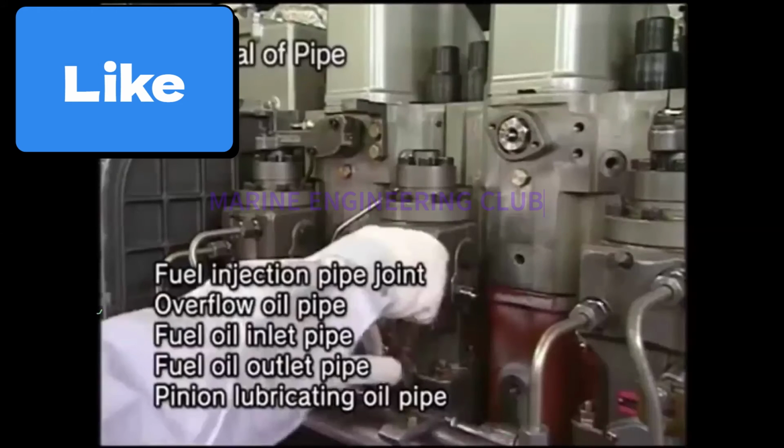The same fuel oil leak off in the main engine we call fuel oil drain, where we have a separate tank. There also they call it leak off, not drain. But there the arrangement is different. When we do the main engine pump tomorrow, at that time we will understand what all the different things are. Okay, let us try to complete this part.